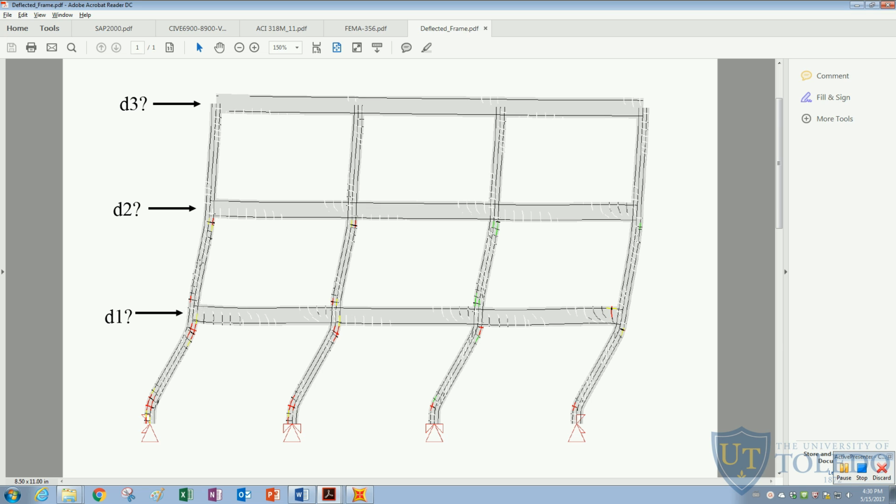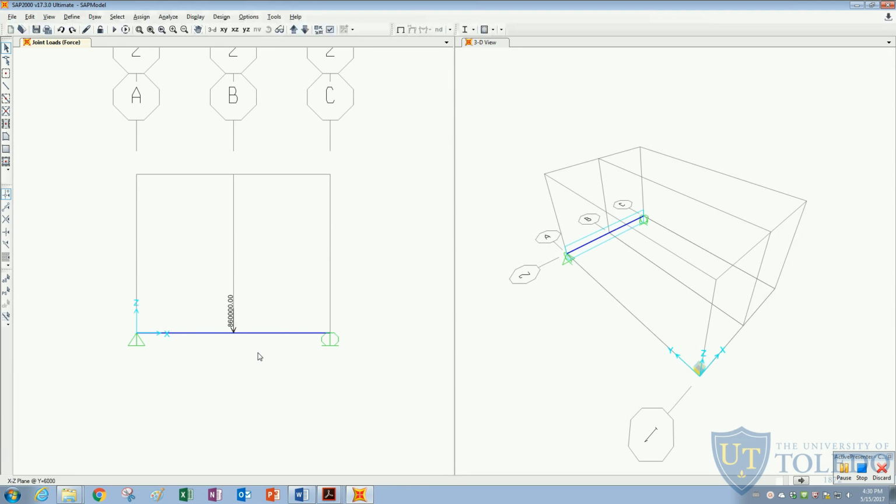So I wouldn't know the values of the displacements to apply here. In that case, we had to use the force-based analysis because the displacement-based one wouldn't be possible. In our case, we only have one point load, so it doesn't really matter. And except for the post-peak response, our response shouldn't vary much between the two analysis procedures.